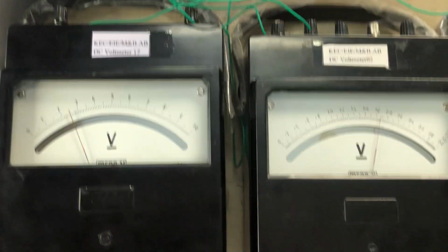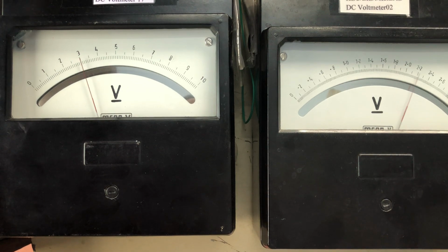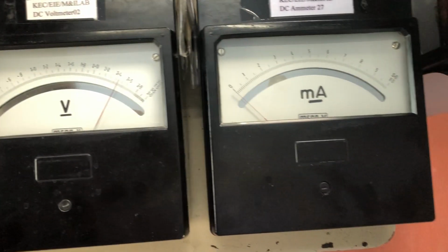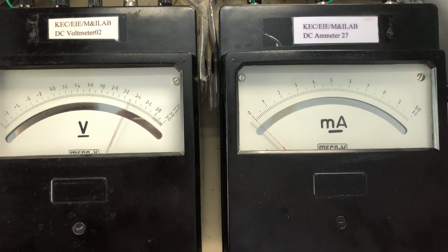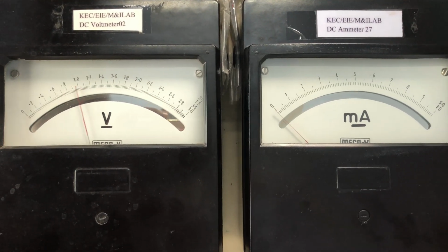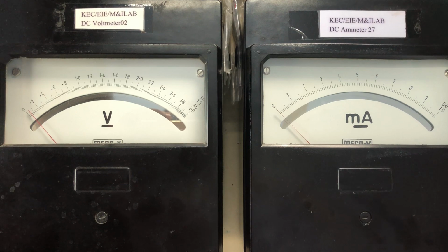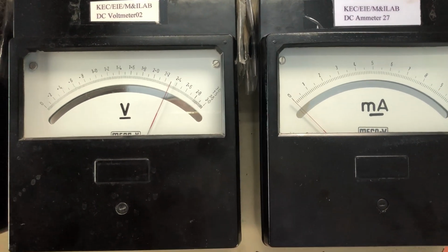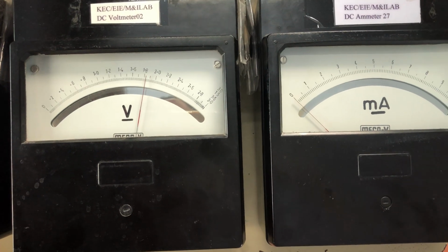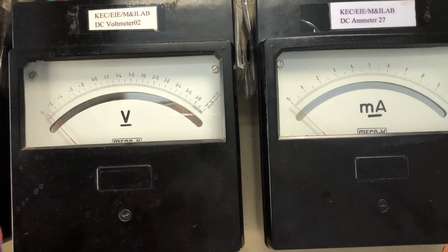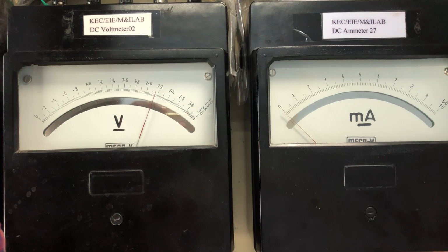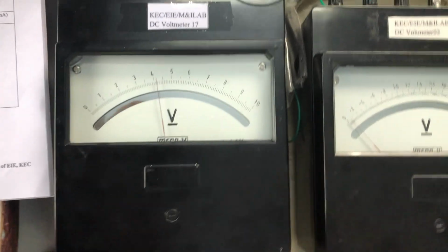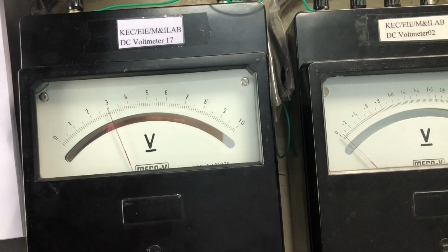Suppose I increase the gate to source voltage to 4, now we will check this. See, whatever you increase the drain to source voltage, your current will be 0, because the depletion regions touch together, so there is no chance of flow of electrons. Okay, right. So this gate to source voltage, we will reduce to 0.